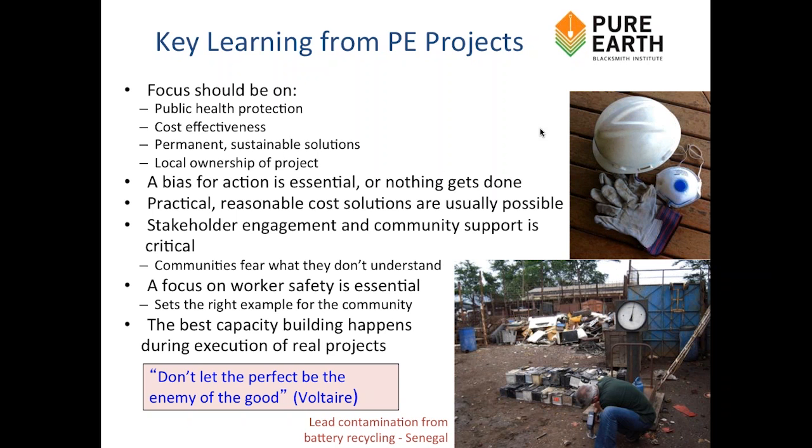It has happened that you have found some more significant lead contamination. You then need to look at your risk evaluation. What is the exposure pathway that is of most concern? When we do that, as I said at the outset of my discussion, you find that the soil ingestion pathway is so dominant that spending money on the drinking water, potable water, is not money well spent.